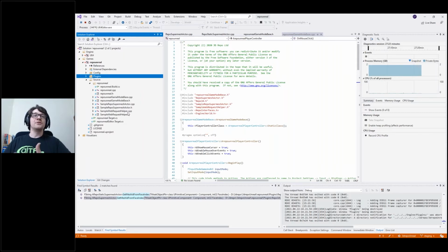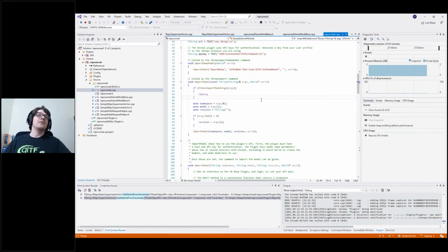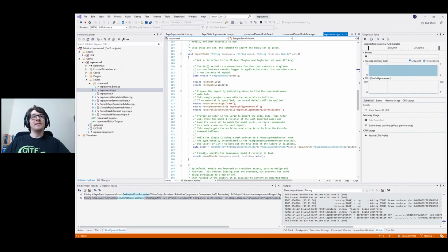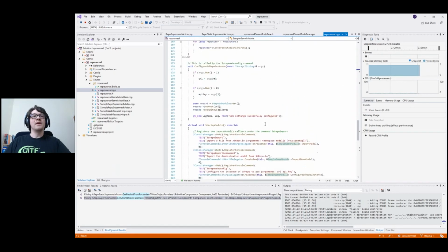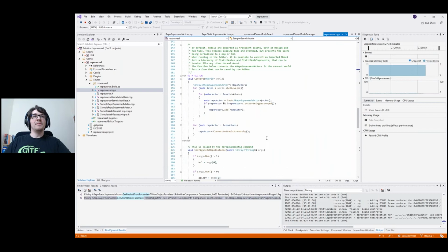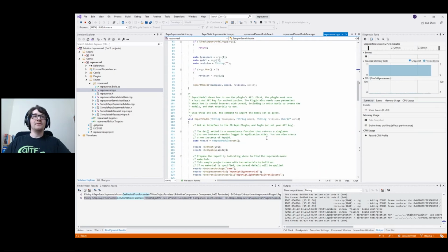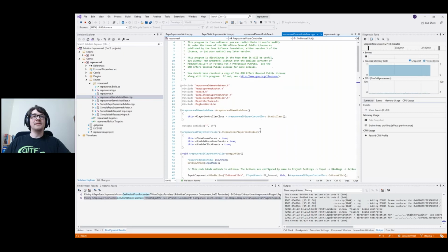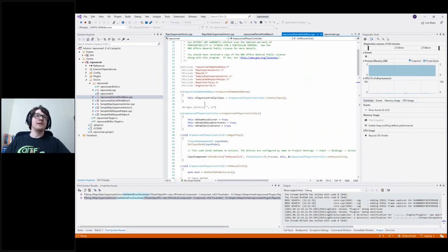In addition to the plugin as source here, I also have a number of example source files. There are kind of two parts to these examples. The first one is our sample game module, and this is, if you like, the minimal working example for bringing 3D repo data into the Unreal scene. And then I also have a number of slightly more advanced examples that show you how to do things like highlighting and picking. These are subclasses of a game mode and a player controller for implementing your logic and input respectively.